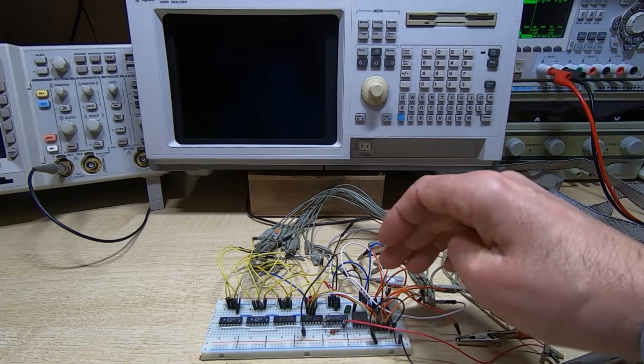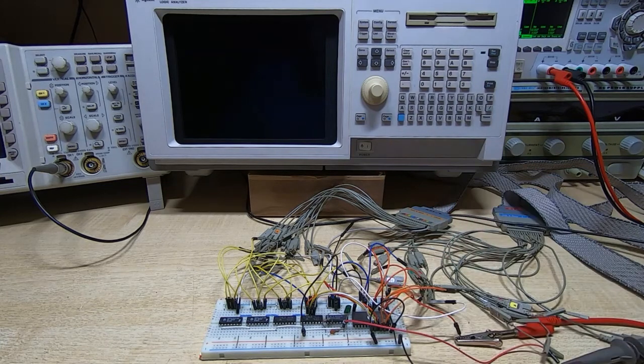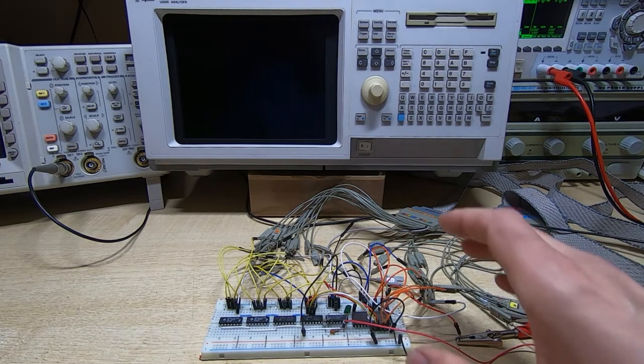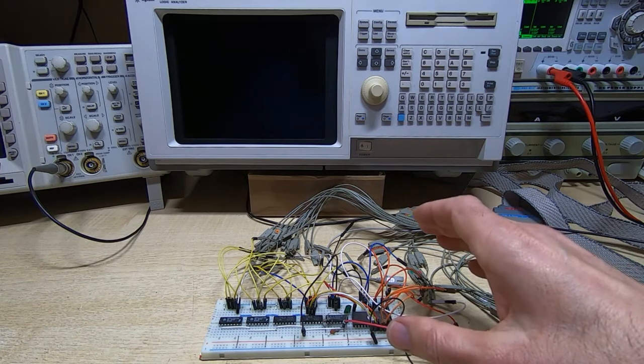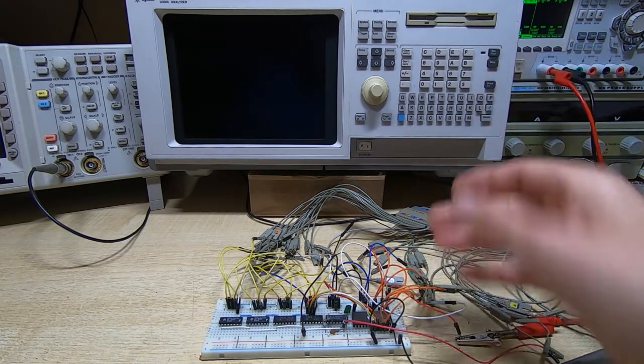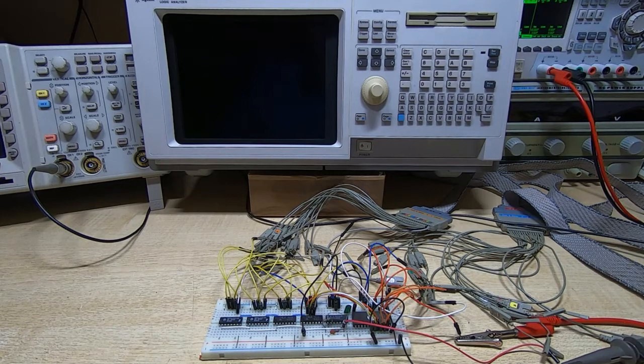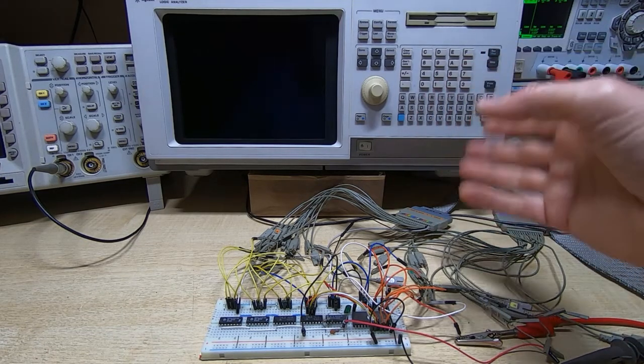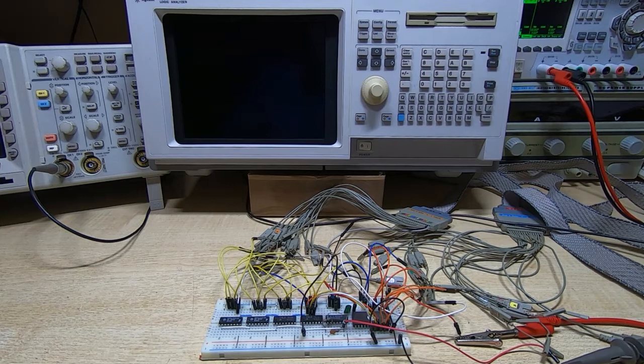So firstly, you have to know something about the target you're looking at when you're trying to do any fault finding. So either use a schematic. If you don't have the schematic, then you have to use the analyzer to do a bit of reverse engineering, but that's part of what you'll be using this sort of machine for.